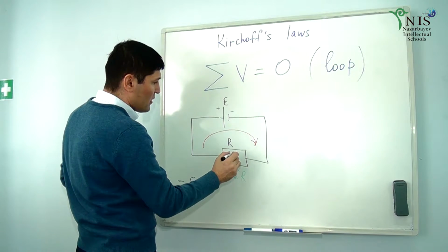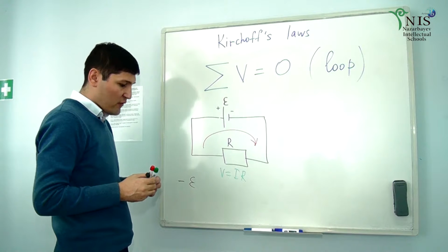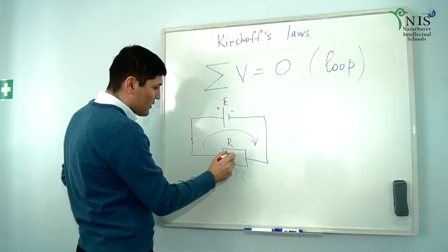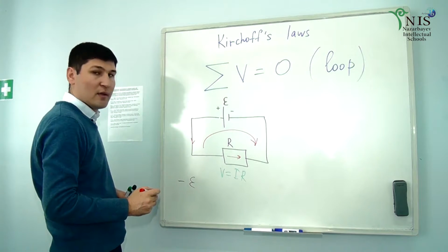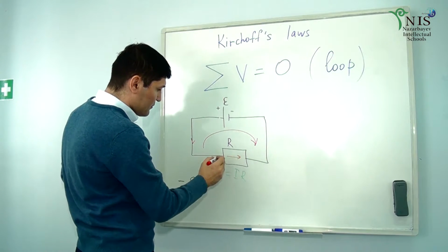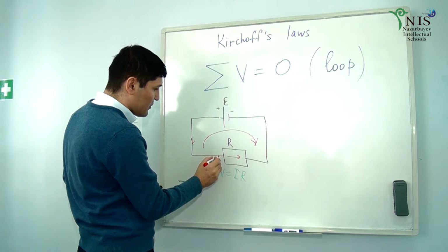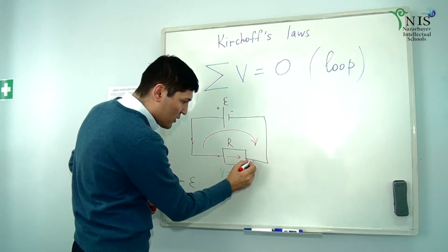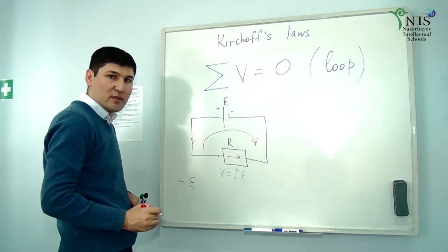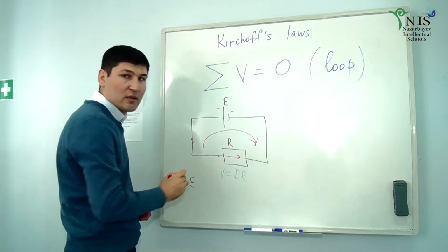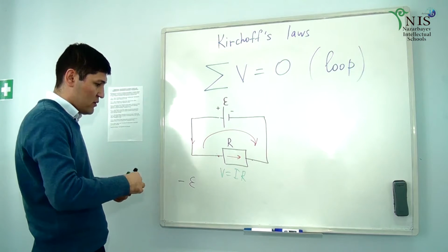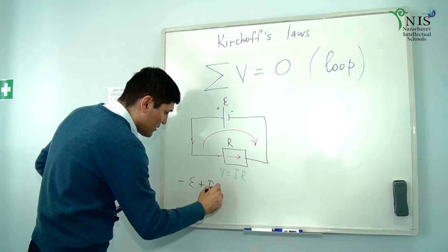And if we go here, it depends on the direction of the current. Current is flowing from positive to negative. Current is flowing through the resistor to the right. But we're looking at this position to the left. That's why the potential here is more than here. Because we are looking clockwise, when we go from right to left, potential increases because the potential here is more than here. Therefore, the overall voltage IR is positive. I times R is positive.